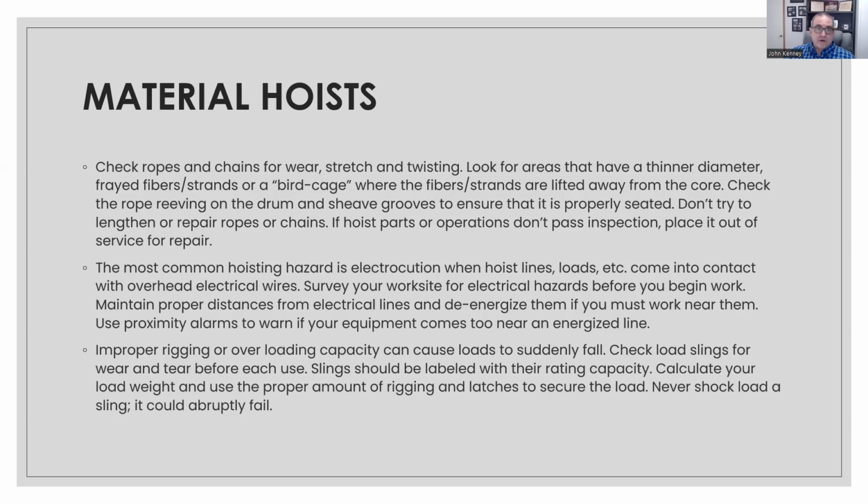So this is not always just when you're hoisting. Keep this in mind when you're working on a roof. If you've got power coming into the building, power arcs 10 to 20 feet. So you've got to take the precautions: either shut the power down or make sure your workers are properly grounded, or that they're in an area beyond where the power is coming in, to avoid electrocution.